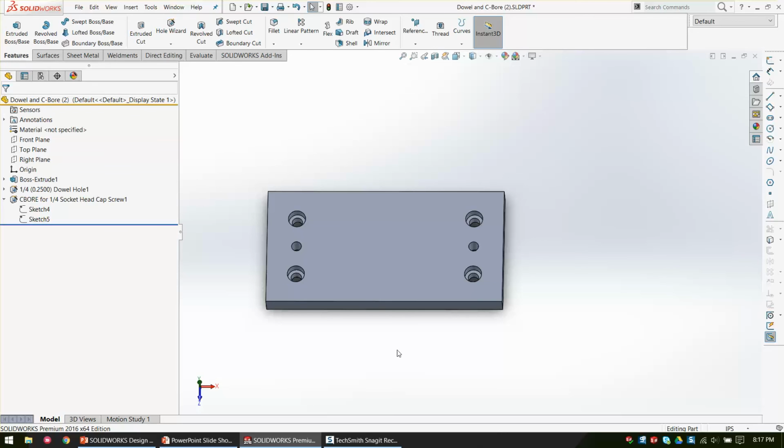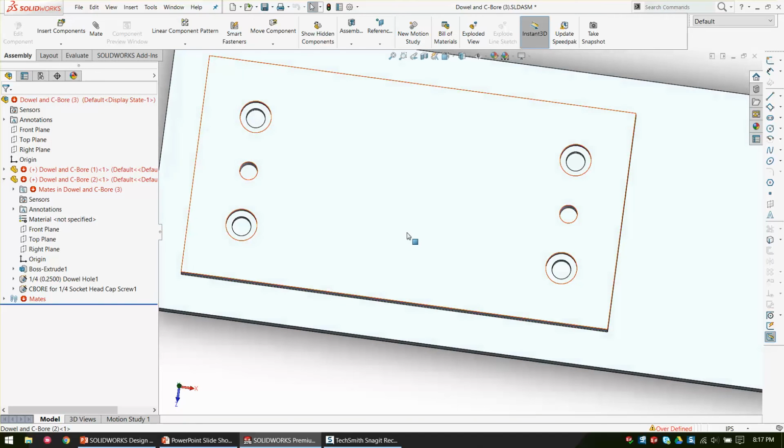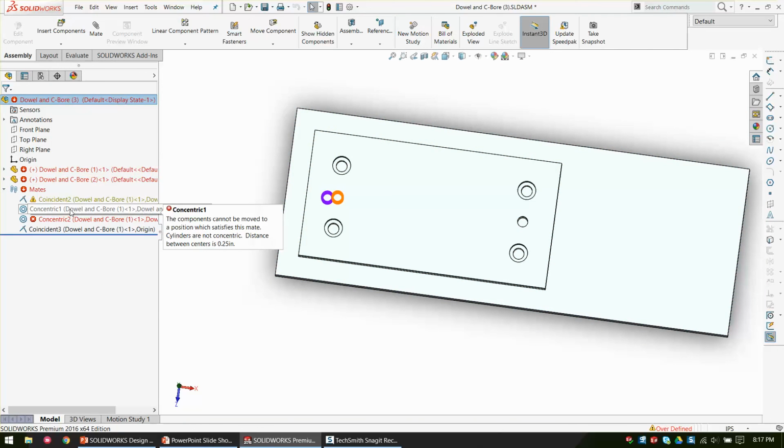And I pick a single spacing, and I always draw my dowels first because my dowels are my most critical aspect. If my dowels line up and my counterbores don't, the machinist can make slots, and it kind of looks like I wanted slots anyway. But if my dowels don't line up, we have problems. And you start bushing things, and it gets real ugly. But if I change that, I want it to blow up. If these mates still rebuilt, you've got a big problem. Because now you have a block that does not match its mating block.